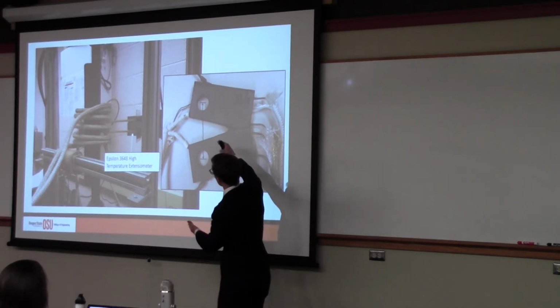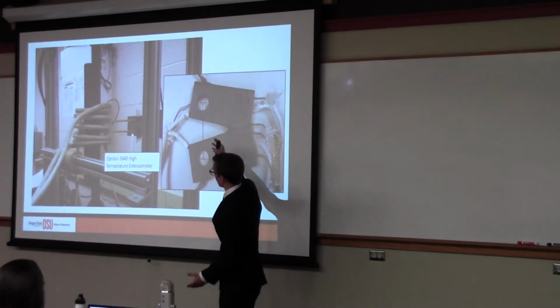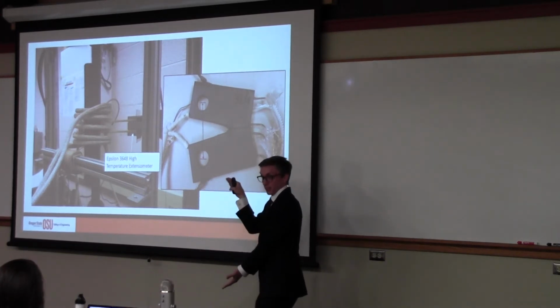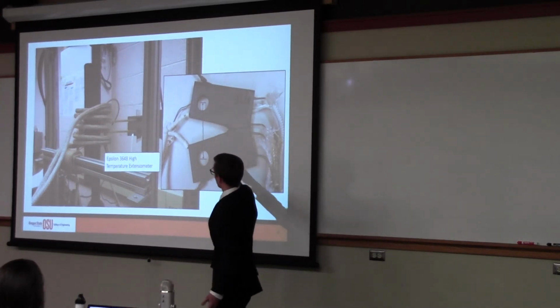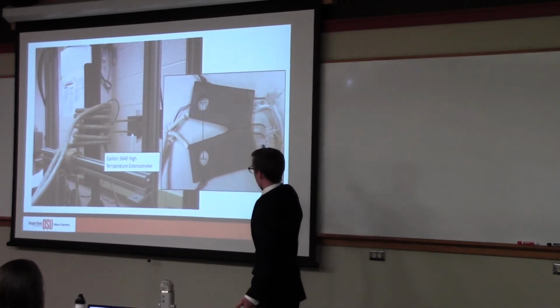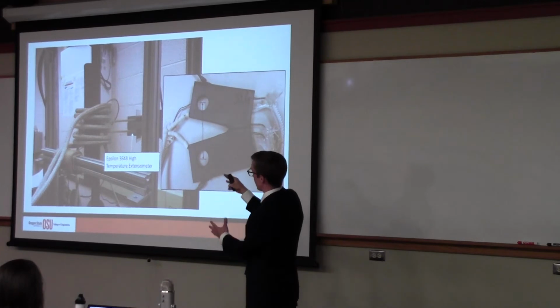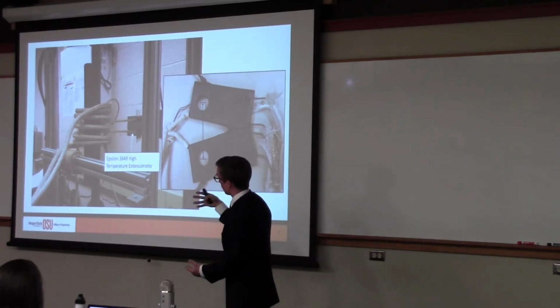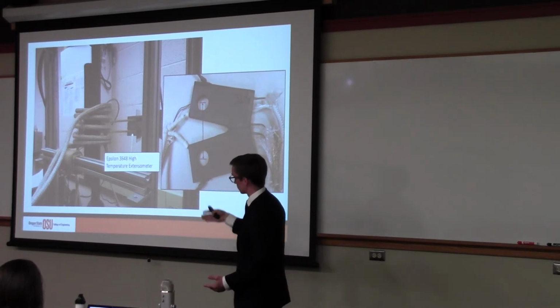And that aspect is the force line displacement, this little line here: how far apart does the sample get during the test, and how fast is that happening? Normally you have a clip gauge attached at the force line, but that's kind of impossible with all the wires we got going on in this thing, how tight things are in there. So what we did was we stuck the extensometer in there and measured the clevis displacement, and that worked pretty well.